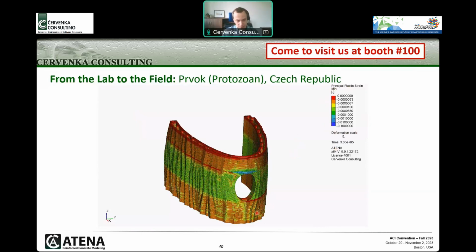You can see that at the bottom there is not much of the damage. However, on the sides, because the printing path was shorter, at the bottom they were printing the whole length. In here it was just going over here and then returning back, so the printing speed is approximately double, so you can see some damage accumulated there.